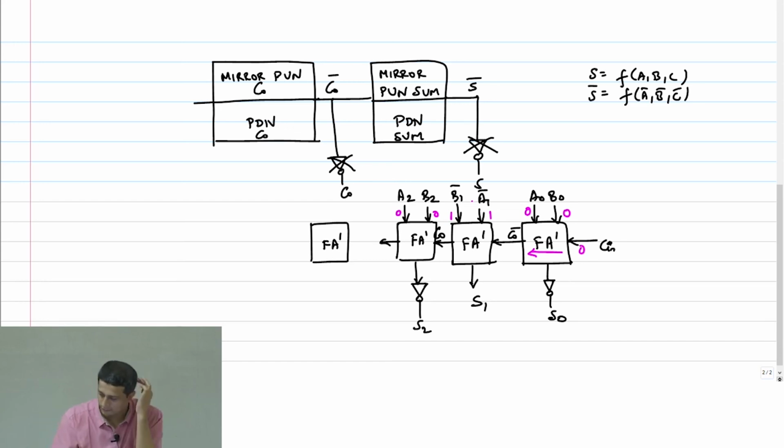Okay, so with that we have done a lot of optimization. How many transistors were there, by the way, in this full adder circuit that we made? Totally how many transistors? In the mirror, in the pull down network of the carry out, there were how many transistors? 5. Right? So I'll put that 5 transistors here, 5 NMOS. Here, therefore, this is also 5 PMOS.